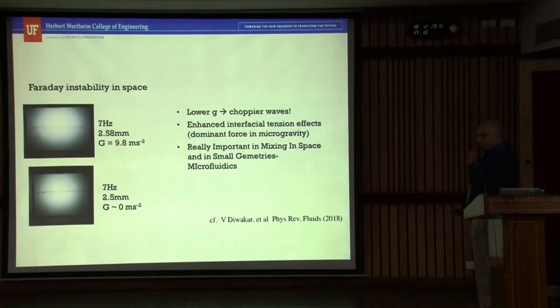We are very interested in using these choppy modes to enhance heat transfer in space-enabling operations. When you go to space, you don't have buoyancy. And heat exchangers, particularly heat pipes, will cause a burnout. So the idea is, can you send acoustic waves? The intention is not to shake a pipe, okay? The intention is to send a signal. So if you can send some sort of acoustic waves, you can start to generate flow.